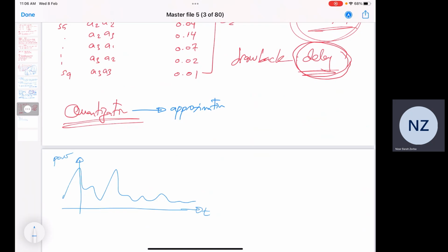So what are the amplitudes for these ones? We know that this is the sampling. How to do sampling? You have learned that there is something called Nyquist. What is Nyquist in charge of? It will tell you each how often you should take a sample, each 1 millisecond, microsecond, 15 milliseconds, and so on, based on the frequency. You multiply by 2, and anything larger than that is enough so that you can fully recover the signal at the receiver. You can revert this operation. Cool? This is what you have seen from Nyquist.